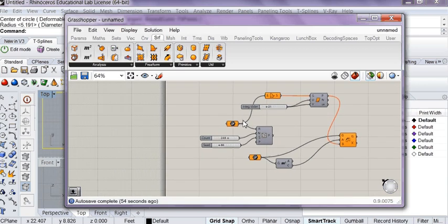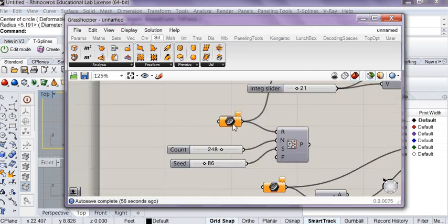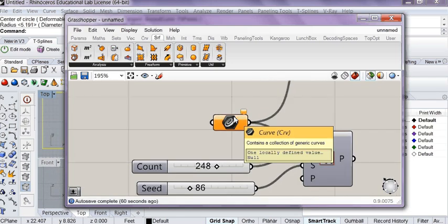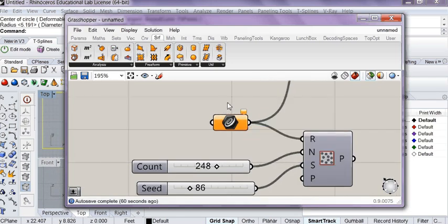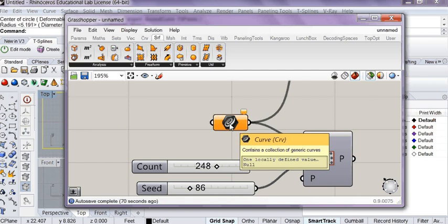Then you see orange color. Do you still remember what's the meaning of orange color? Why is it orange? Any ideas? Well, it's not connected to the content. Yes, so it's missing the content, right? Most likely when you copy code from others, this content is pointing to some other geometries which is not in your file.